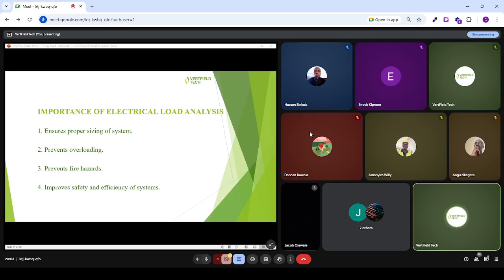So that is the importance of the backup time. The backup time is a standard parameter which is used to size the battery system. When we get to sizing the battery system, for those of you who have made your payment, in the next class, you are going to see how the backup time plays a vital role. The backup time would be stated by the client, and then you use it to know how many batteries or what size of batteries would be able to run for that length of time. I hope we are clear, sir.